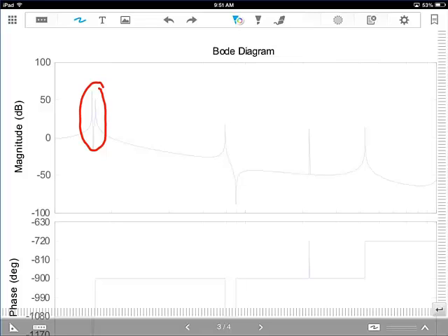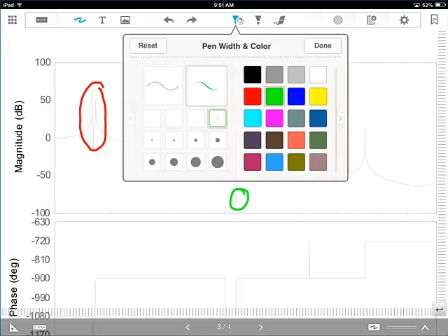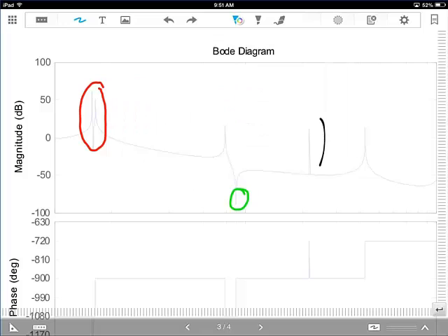We're looking for the zero here. And again, you have omega 4 out here, which is sort of a pole zero cancellation, as you'd expect. So this is the zero we're looking for. This means that if you excite this nodal beam at that frequency, you get almost no transmitted load to the ground.